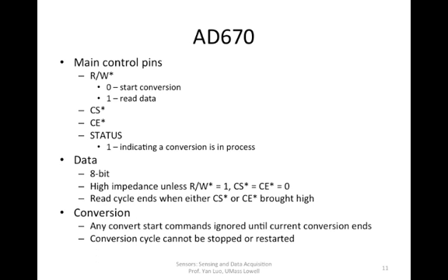The next one is the status. It's another pin, it's a 1-bit. It indicates the current status of this ADC, with 1 indicating a conversion is in process. So you have to wait until this status becomes 0, which indicates the completion of the conversion.